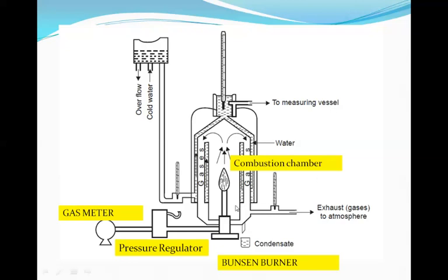Now the exhaust gases pass out to the atmosphere, and again the temperature of these gases coming out can be noted, and the condensate water droplets are measured. Then the quantity of the steam condensed is calculated, and this is utilized for measuring the LCV value. Now for the HCV and the LCV values.